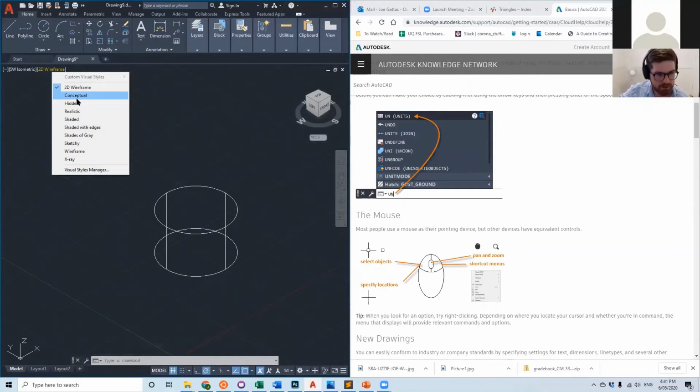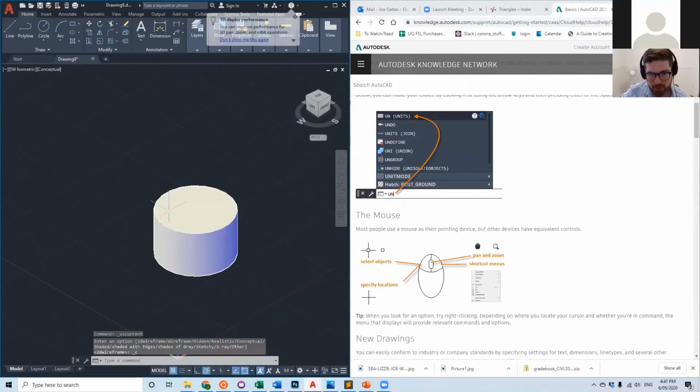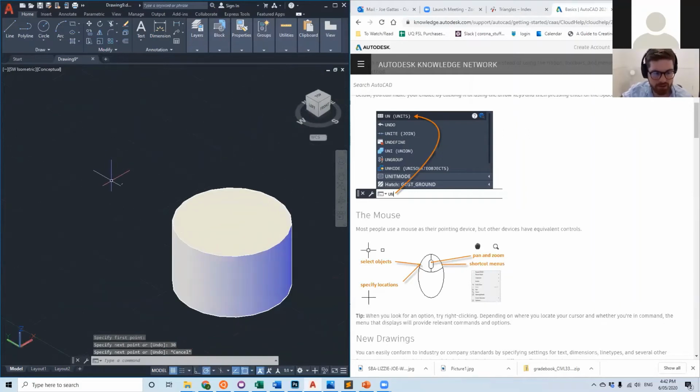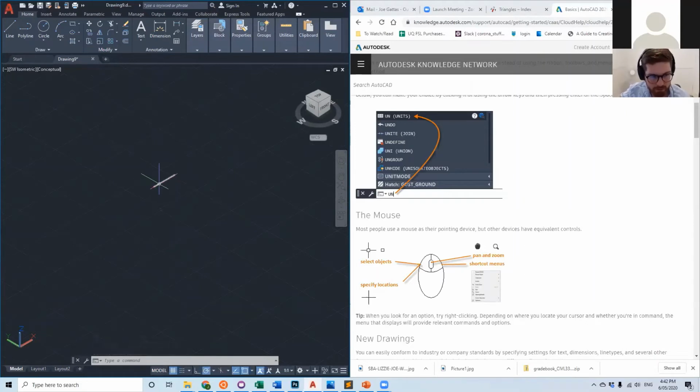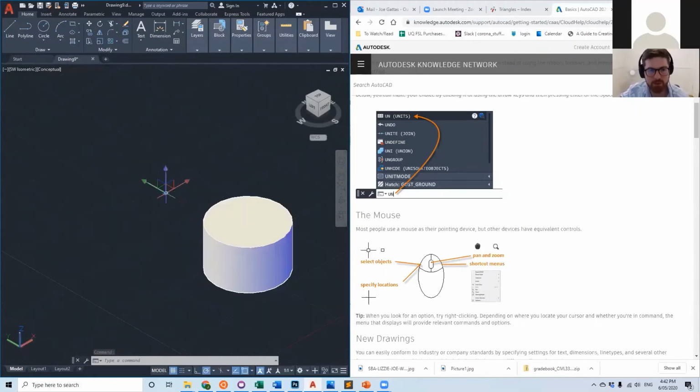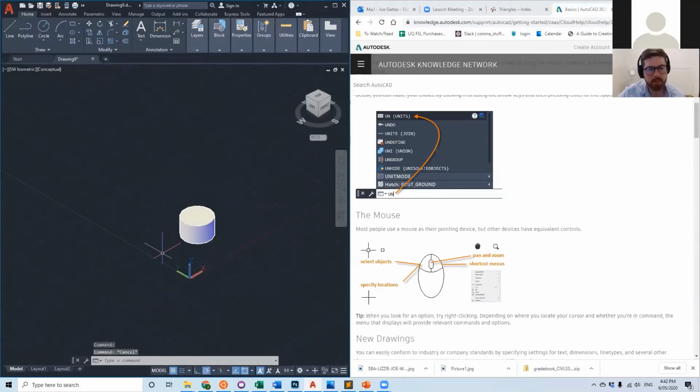Once you start drawing things, or even before you start drawing things, you need to be able to navigate the viewport. One of the main problems that I have when I'm trying to draw CAD is I'll start using the software. I'll type in a number, which I think would be good, something that's 30 meters long, and then it doesn't look like I've done anything because I'm operating in units that are inappropriate. So I thought I drew something that was 30 meters long. I've drawn something that was 30 millimeters long, and I'm zoomed out to a scale of meters, right? So number one frustration that you'll encounter trying to use these softwares is just a mismatch between the units that the software is set up to deliver and what you're actually trying to do.